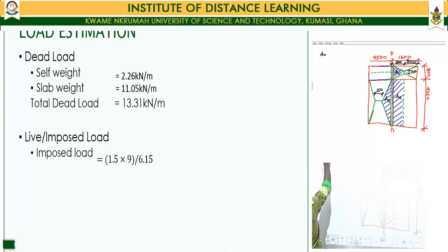And so in calculating the area, our formula becomes half (A plus B) multiplied by H. This is equal to half of (1.8 plus 0.2) multiplied by a height which is equal to 0.8. This gives us a total area of 0.8 meters squared. That is for our area 1.